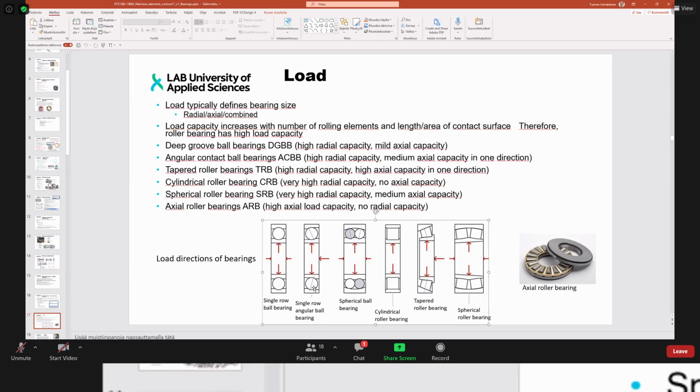Yes, exactly. So the spherical ball bearing system is allowing the free deflection of the shaft. Whereas with the single row ball bearing, if your shaft is deflecting, it quite rapidly highly loads the other side of the bearing raceway, on the top and on the opposite side on the lower part.